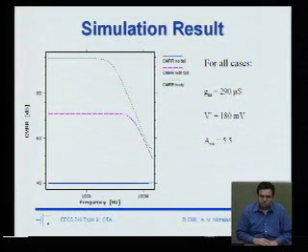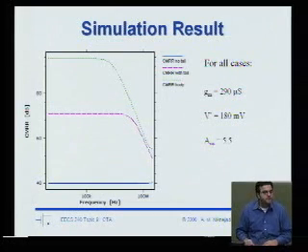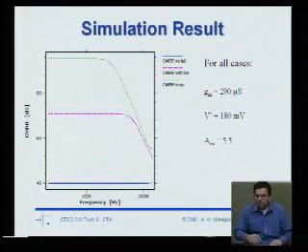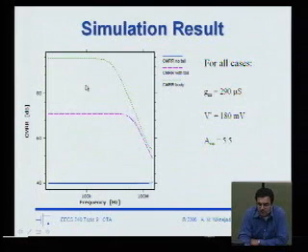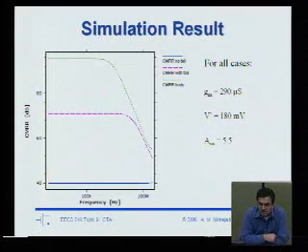And if you've got capacitance sitting there at high frequency, that's going to basically reduce the degeneration, and so the common mode rejection ratio will go away. Fortunately here, if the transistor is not too big, then you actually get it all the way up to maybe even the signal frequencies where you care. Okay? And then finally, this is the PMOS device where we've gotten rid of the body effect, and now we see huge common mode rejection ratio, right?